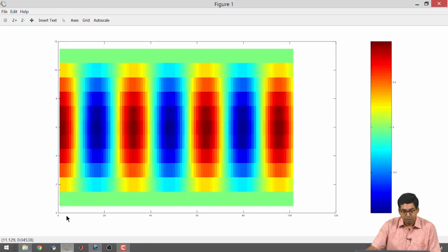So, now this is your z direction, and we are plotting for a slice. So, this is your x direction going here, right. We have picked up m equal to 1, okay. It is saying that if you pick up m equal to 1, and n equal to 1 is what we have picked up and we have taken a slice right in the middle of the waveguide. M equal to 1 is telling you that you are going to be having a spot in the middle of the waveguide. And along the z direction, it is a travelling wave.